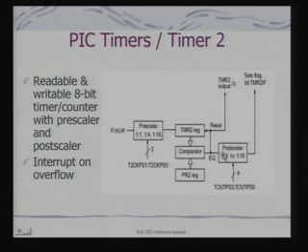And a postscaler means what? The postscaler also can be set to different values for post scaling the output of timer 2. And these bits that we are showing here are some of the control bits which can be set to set the different values of the prescaler as well as the postscaler. In fact, this timer has a very interesting property we shall see soon, and we have just shown a glimpse of that property here, but not exactly how it is used in the complete context.